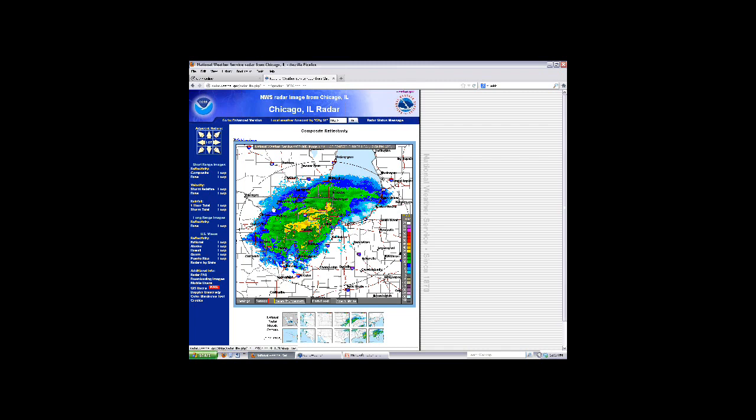So in terms of the Weather Service radar and our radar, we inject test signals backwards. We send a known signal level through the H and V receivers and monitor whether the response of the receivers is drifting with time. The Weather Service is doing it when they do these scans, like I've described here, from low elevation. They work their way up to some high angle, maybe 19 degrees. Then the antenna drops down to begin the next volume scan. And while it's on its way down, the Weather Service is injecting a series of test signals into their receivers, so they get a measurement every few minutes of how those receivers are behaving.